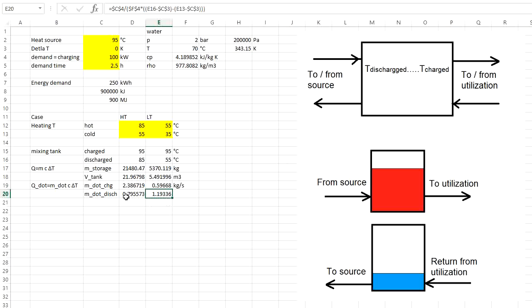One possibility for the discharging case is that the mass flow rate would not be changing, it would be at these higher values, and here it would be a shortcut with the three-way valve that would mix some of the return temperature back to the outlet to the heating to have it at the constant 55 degrees C.